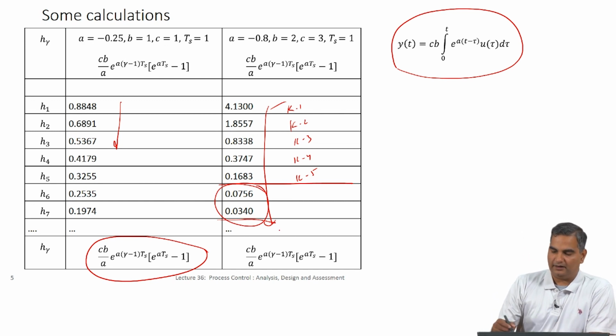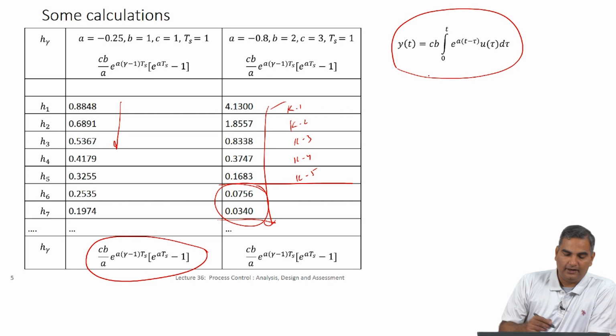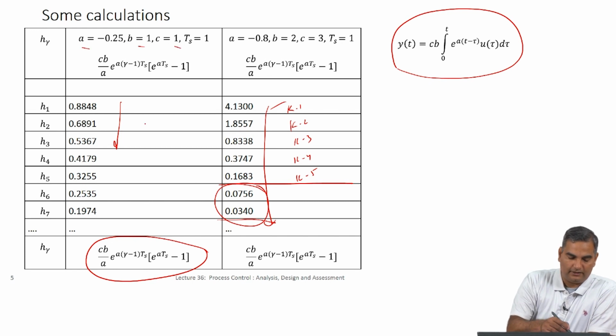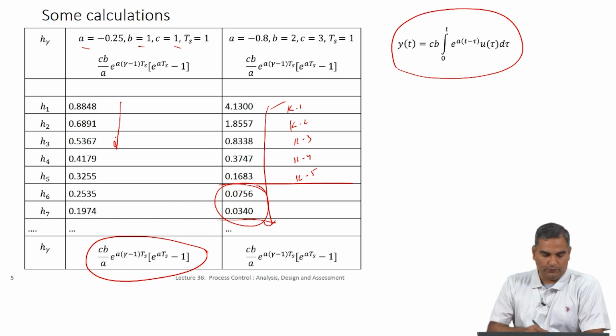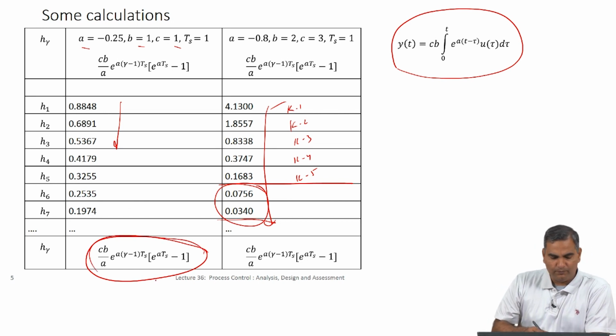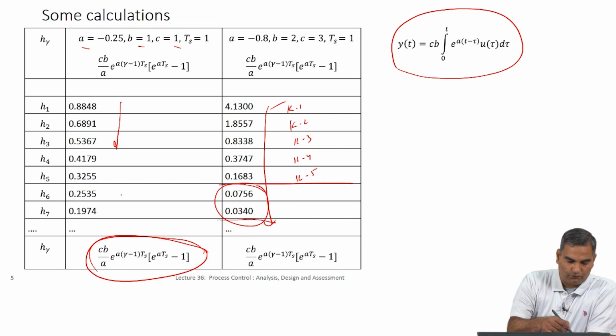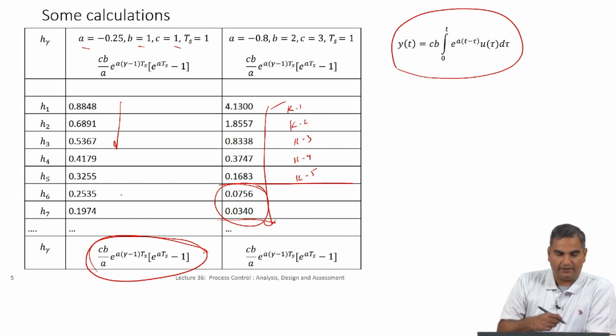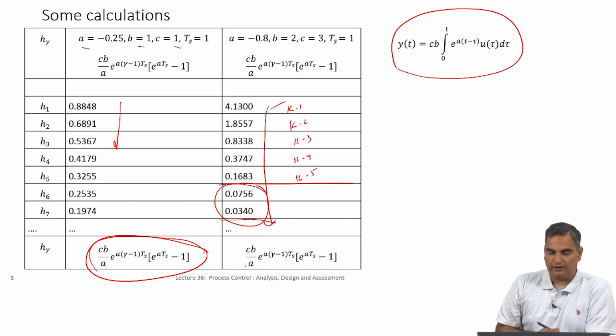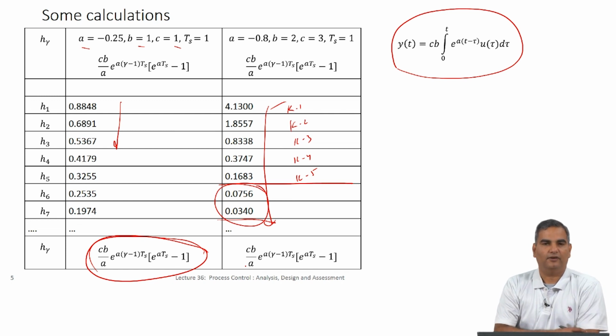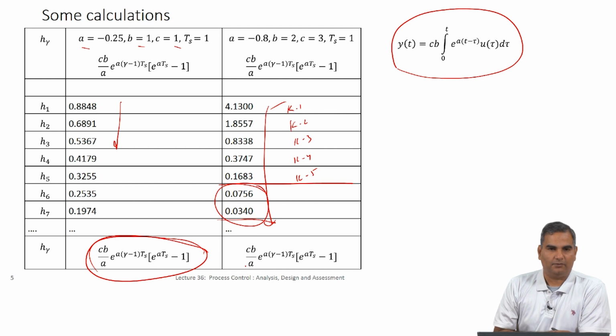But this tells you that for typical systems where we had the state space models and I have taken some values for A, B, C and then actually shown the computations of H, how this formula is derived I have not told you, but I have just told you that if you were to compute this, it will keep going down. At some point the memory effect will kick in and these coefficients will become smaller and smaller, so that adding them in the model does not give you any purchase. So, this is the basic idea of how you derive a discrete model and how you think about a discrete model, which we are going to use in a model predictive control framework.